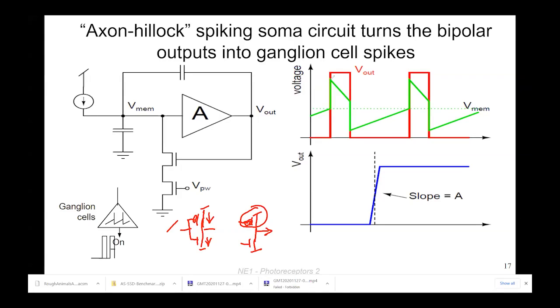And by the way, this picture is wrong, right? There's no reason that it should switch when it gets to this point. This should actually switch when it gets here, and charges up again, and it switches down here again. The amount that it charges up here through the cap divider should be exactly the same as the amount that it charges down on the other side.